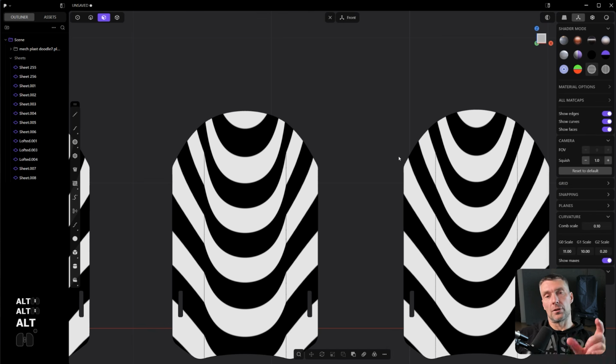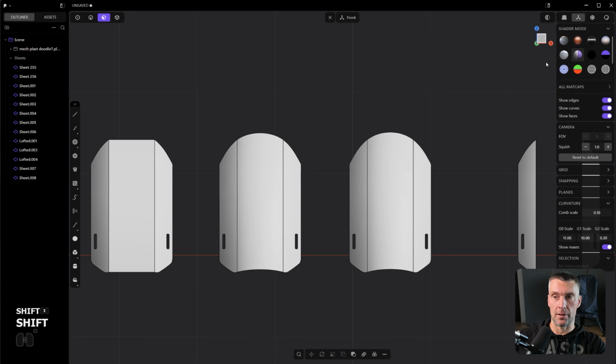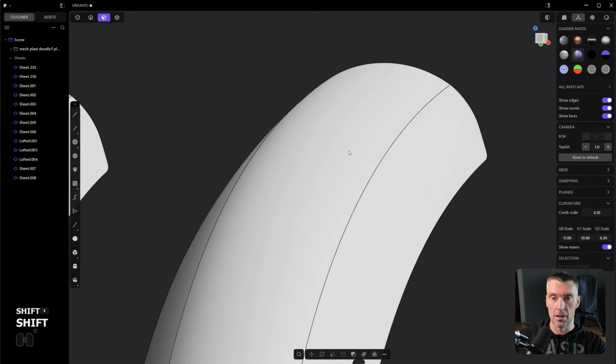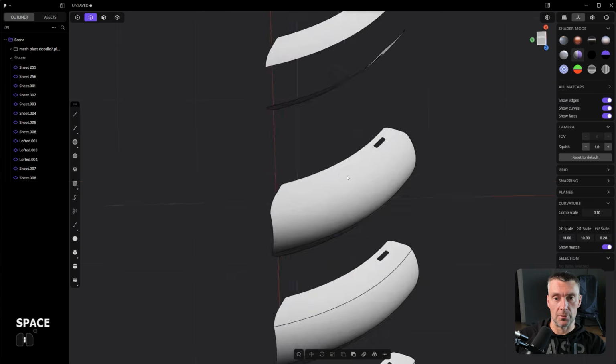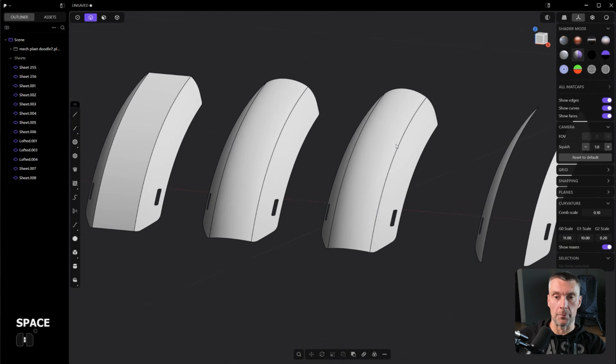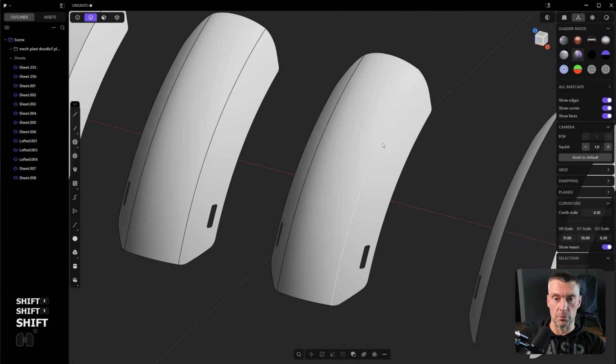And now you can drive A-class surfaces in Plasticity, and you can actually measure it, which is really cool. So if you want to create some really high-end designs for, like, BMW or whatever, or some really high-end designs for NASA, where you really need smooth surfaces and the transition between two surfaces needs to be mathematically precise, you can actually determine this by measuring the curvature comb on the edge and measuring the continuity between two surfaces.